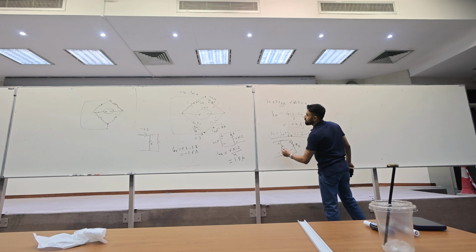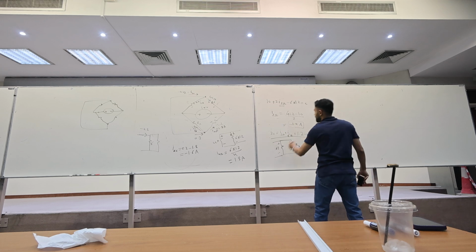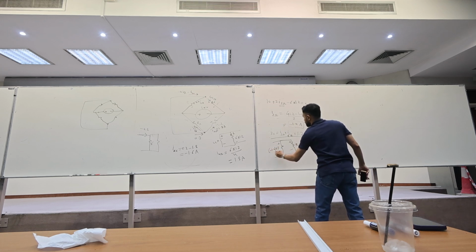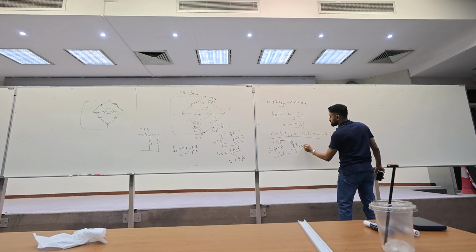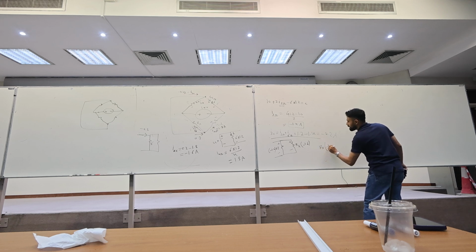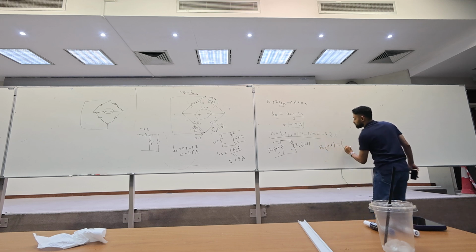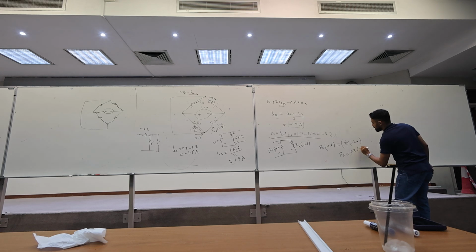And what is this 2? What's the current at 2? We already calculated I2 amp, minus 1.4. And I already know what's IRX, minus 1.6. So Rx times minus 1.6 equals 2 times minus 1.4. So what is Rx? 2 times minus 1.4 over minus 1.6.